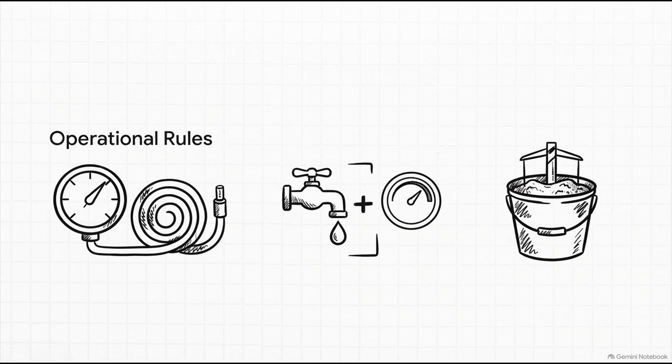For dry mix, your operating air pressure should never dip below 60 psi if you're running 100 feet or less of hose. On top of that, the dry mix water pressure at the nozzle has to be at least 15 psi higher than your nozzle air pressure so it actually injects properly. And what about wet mix? Well, you're generally looking for a typical nozzle slump of 2 to 4 inches.